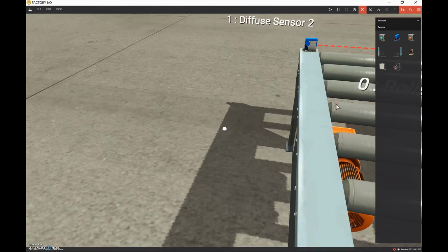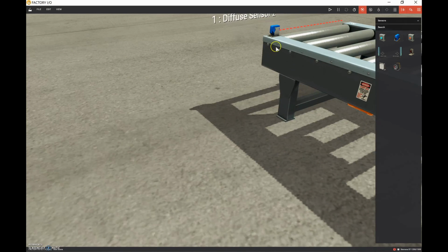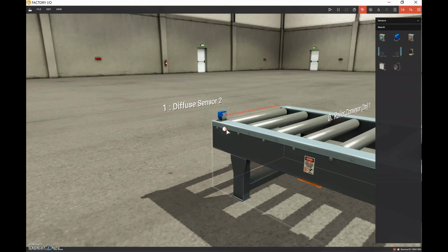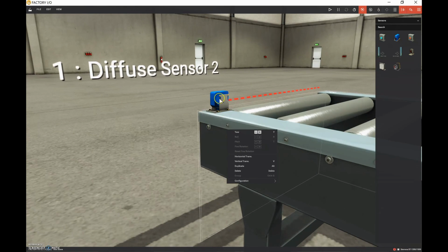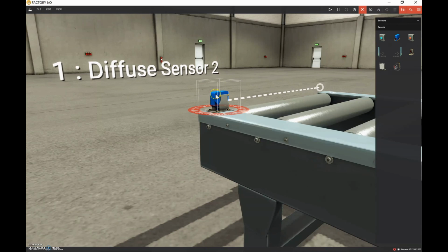And we said that we're going to create another sensor. So what we need to do is just zoom in here, and then click on this guy until you see a box around it. And then you've actually selected the sensor rather than the conveyor. Now I can hit the Alt key and left click on this guy. And then at that point, you're like, maybe I made another sensor. I can't really tell. But you can see that there's this red hue around here. And you might just be able to make out that there are two different tag numbers superimposed on each other. So we have created another sensor. It's telling us that one is sitting on top of the other because it's got that red hue to it.